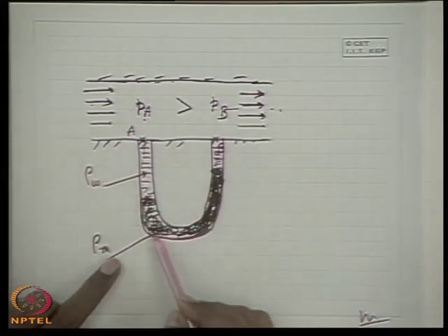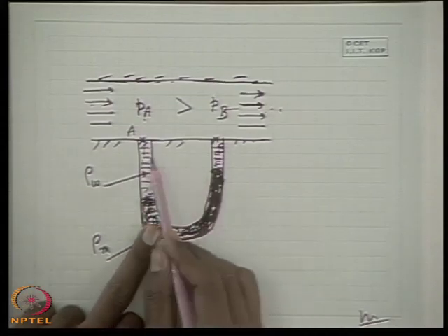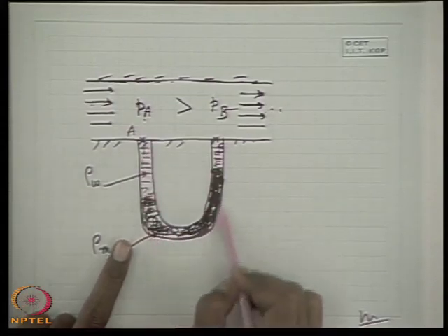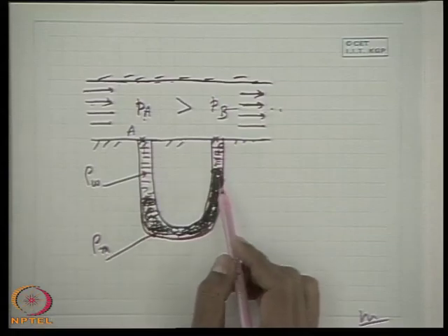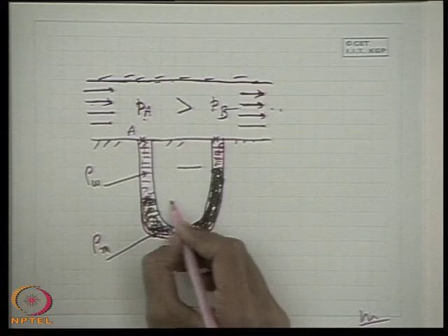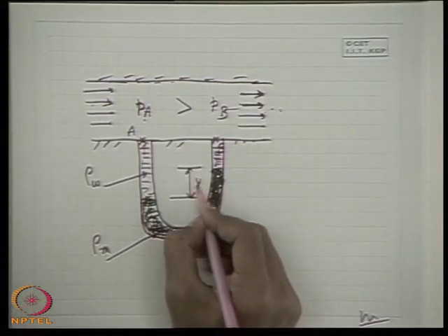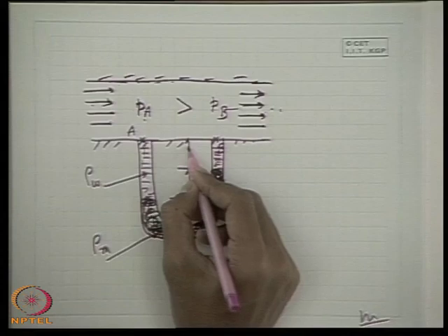But whenever we use a very high density fluid, which gives a well defined meniscus with this fluid, then what will happen? Automatically this will come to a static equilibrium because of the pressure balance. Then the situation will be like this. Let the difference in the meniscus, or the elevation, read as y and let this be x.